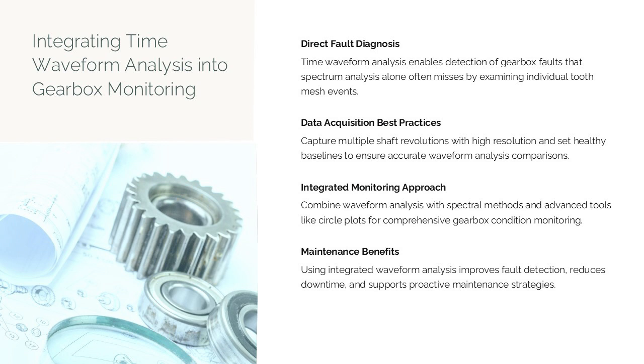Best practices include configuring data acquisition parameters to capture multiple shaft revolutions with adequate resolution, establishing healthy baselines for comparison, and using waveform analysis alongside spectral techniques rather than as a replacement. When combined with advanced tools such as circle plots and time synchronous averaging, waveform analysis becomes a cornerstone of professional gearbox condition monitoring. Implementing this integrated approach improves fault detection capability, reduces unplanned downtime, and supports a more proactive and cost-effective maintenance strategy.